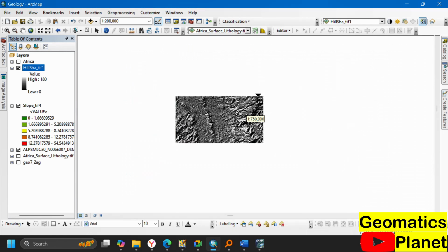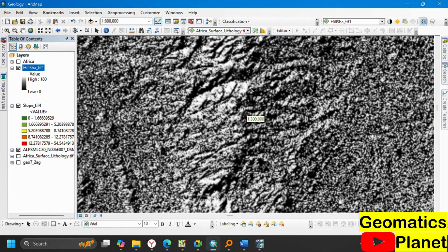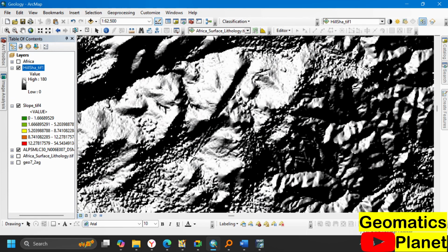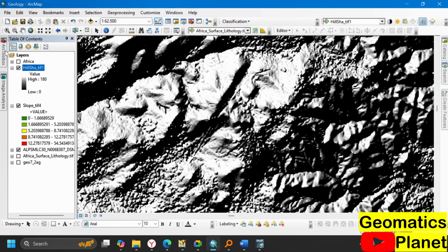So this is a way you can use the digital elevation model to create a slope and also to make a hill shade, and this is how you are going to get it done. Also, there are several ways you can improve a map if you're producing one. Like what I showed us, we are going to use Blender. Blender is software you use to make your map look better. So we might also be using that. It is part of the map I shared with us, so we can finish up with this and overlay it to visualize a map that looks more aesthetically clean or better.